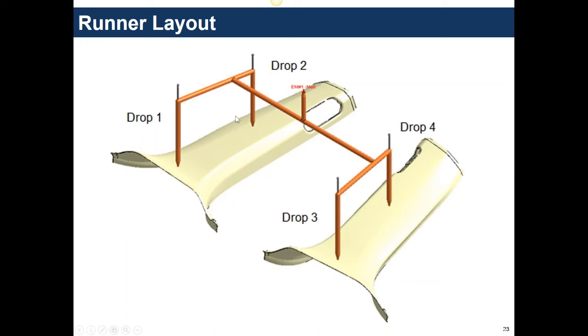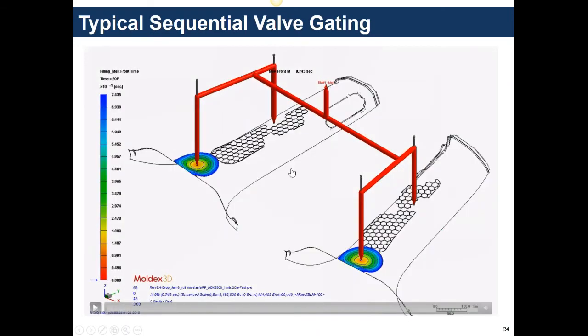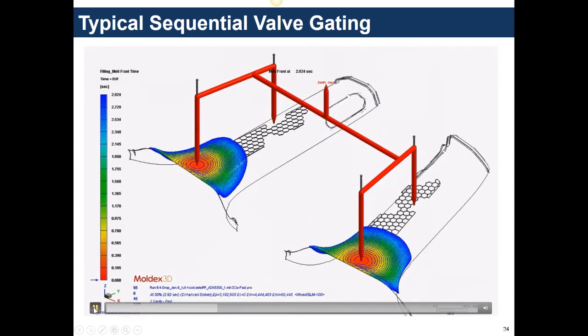But when we're doing so, we assume that the gate is either closed or fully open. And you could not really simulate opening and closing of the valve gate. Okay. So now, software has been developed, technology has been developed where you can simulate opening and closing of these valve gates, and you can control the velocity of how fast these gates open and close, which is why now you can predict this sort of a hesitation when that gate opens.